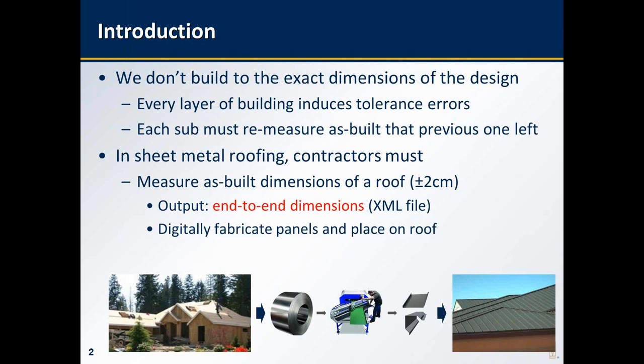In general, as you know, in the construction industry, a structure always has tolerance errors, and it is never built to the exact drawing dimensions. Every subcontractor must measure the work that the previous subcontractor has done in order to be able to do the work that he is supposed to do in the project.